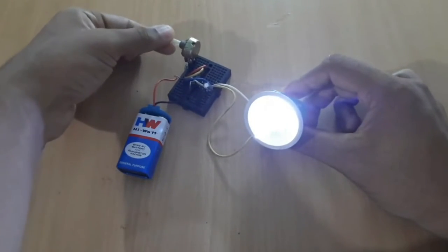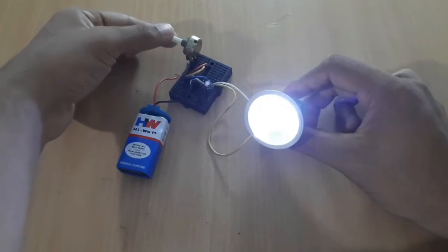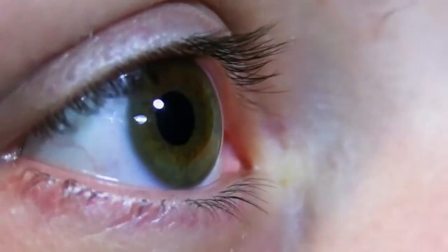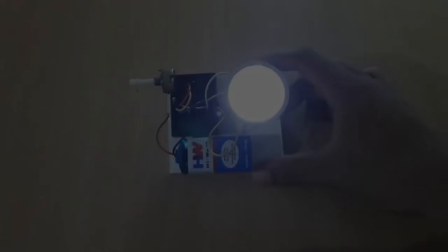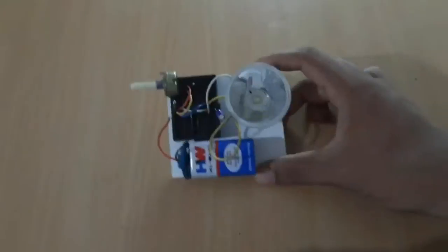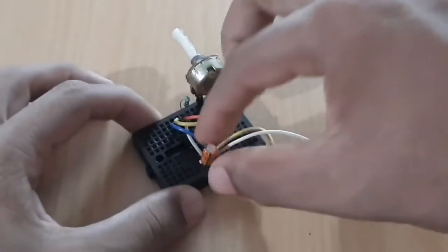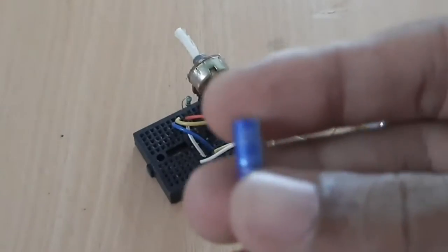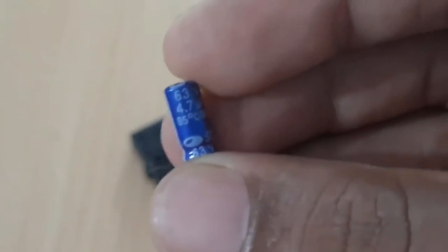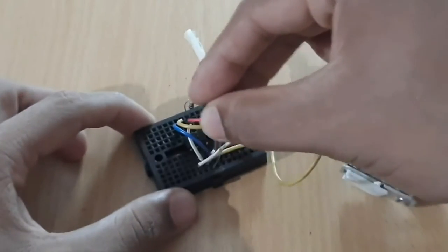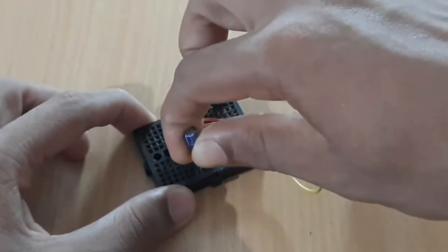As a rotating object, I used a DC motor with a cardboard on it. Then the difficult part of the project starts, the adjusting. As the blinking rate of the LED was very fast, it was really a painful experience. But after spending 4 hours, it didn't work well. So I decided to replace the 10 microfarad capacitor with a 4.7 microfarad capacitor. After a bit of adjustment, I got a slightly slowing effect. It can be called a 60% success.